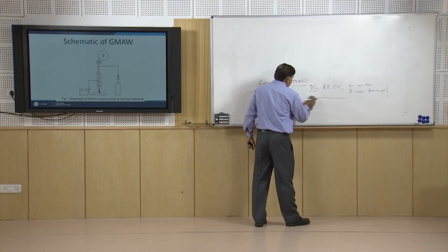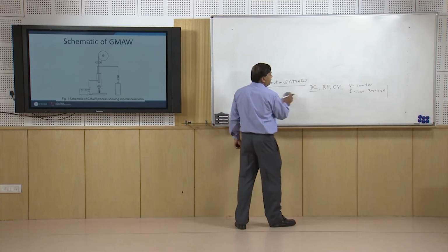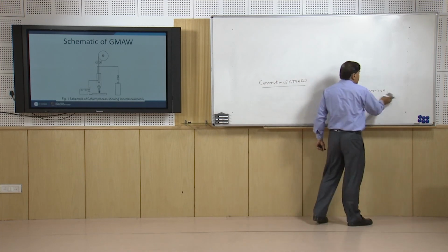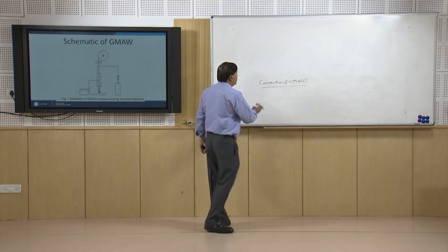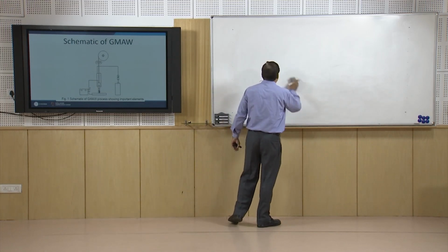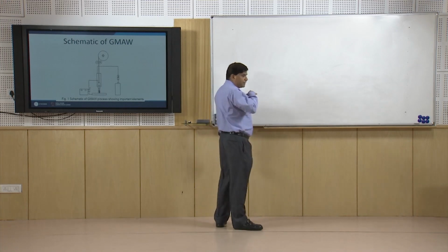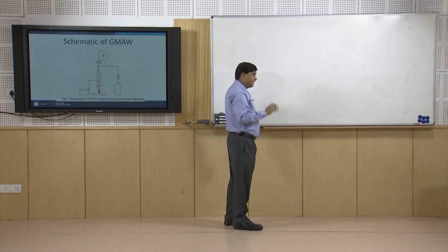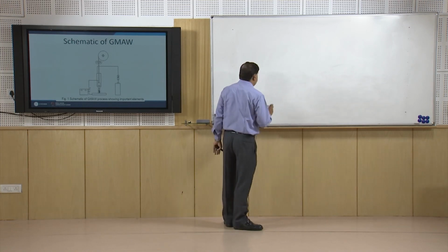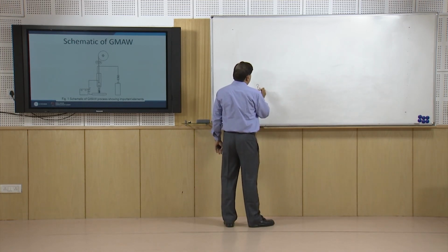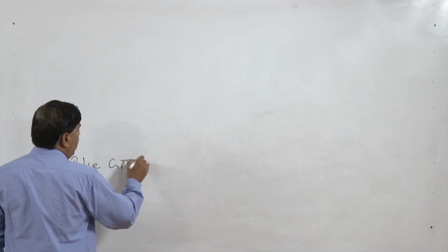But in some cases, when we intentionally want the heat delivered to the workpiece to be limited in order to avoid its related adverse effects, the process is modified intentionally. In that case we do not deliver constant current like DC, but the current magnitude is controlled in a particular manner, and for that we use the pulse GMAW.